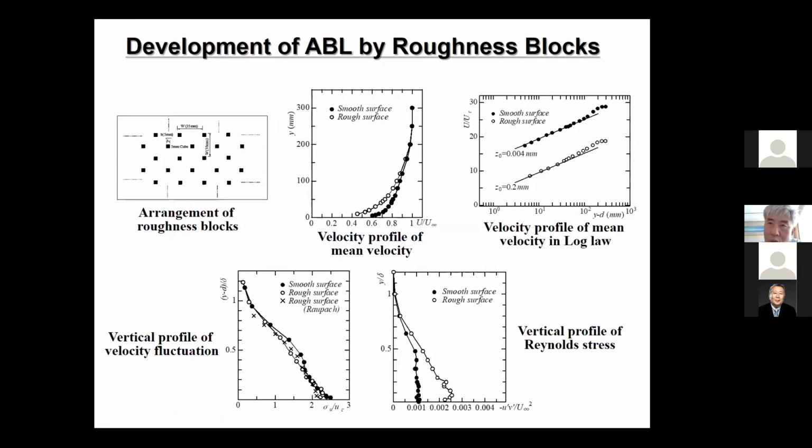So usually for wind structure analysis we use this, but for environment studies, usually people will consider the flow very close to the ground. So we use a log law to estimate velocity, with some dominant parameters like Z0 in the wind tunnel test for environment studies. And also we consider the Reynolds number and also sigma U to simulate how the roughness blocks contribute to developing the turbulence.